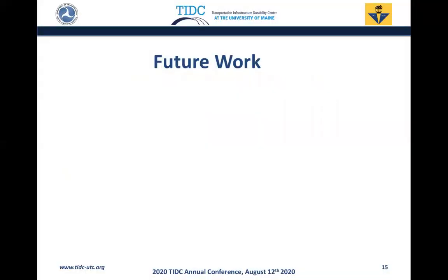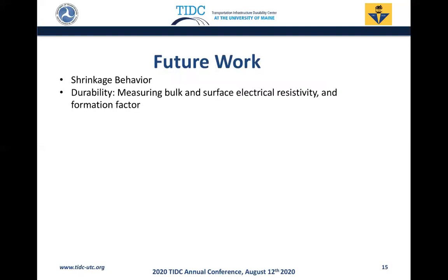Future work will be studying shrinkage behavior of these concretes improved with slag and CO2. Studying durability performance, it means, for example, we are planning to measure bulk and surface electrical resistivity of our specimen, and then calculating the formation factor as an index for durability.